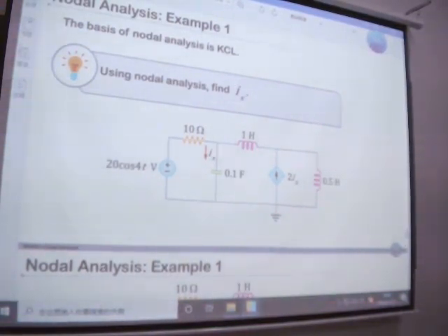Okay, j omega, j is still j. If you put the minus here, the j should be in the denominator. Minus j, j is here. Omega C, what is omega? 4, just put 4 inside. Minus 0.1. So the value should be minus j 0.1.